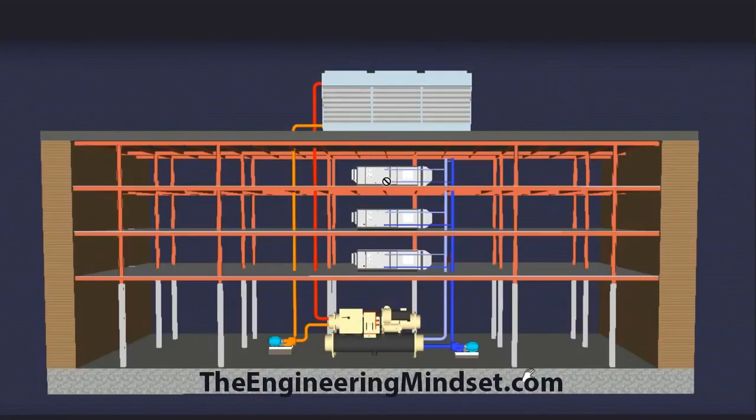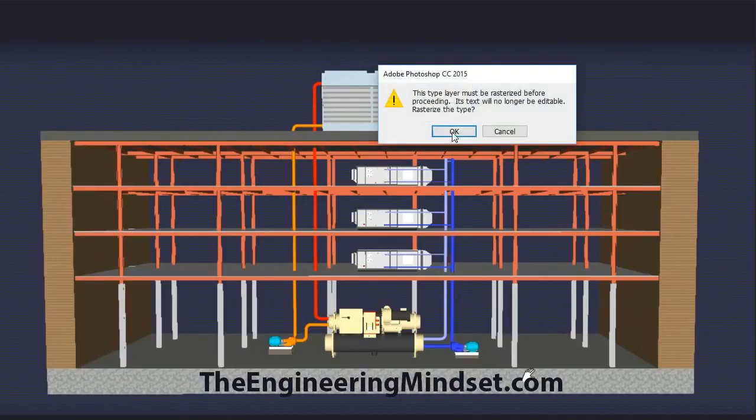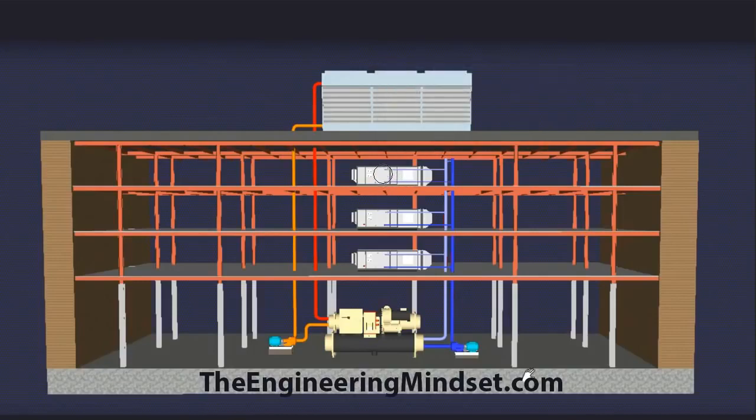So that warm air which is returned enters into here, gives up its heat, so it transfers the heat from that into the coil of cold water, and the cold water gives off its coolth into the air, so it comes out as cold air here, and that obviously raises the temperature of that water, and that then returns back to this riser into the evaporator of the chiller, where it then gives off its heat into the condenser side of the chiller.